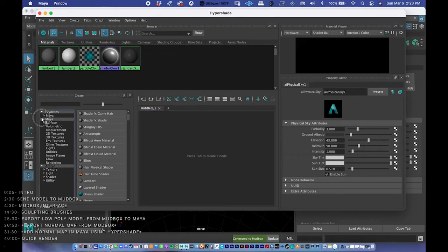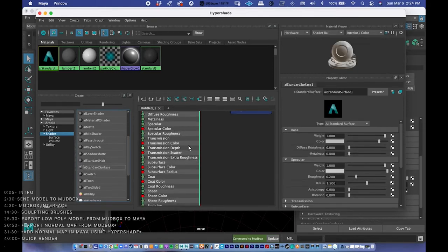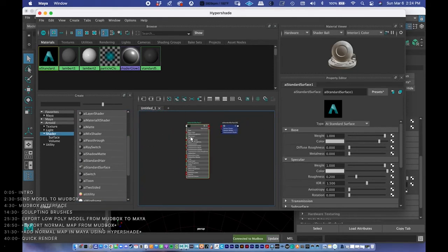So I need to use a specific material here. I'm going to go to Arnold, Shader, click on where it says Shader right there. Go down to AI Standard Surface, and it should have a little A on the top right of it. AI Standard Surface, this is pretty much by far the best material in Maya, and you can use it to make metals, plastics, any kind of material. You can get it with this shader right here. And definitely want it for this technique I'm showing today.